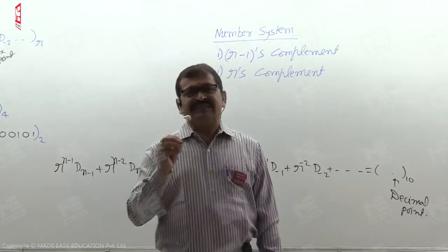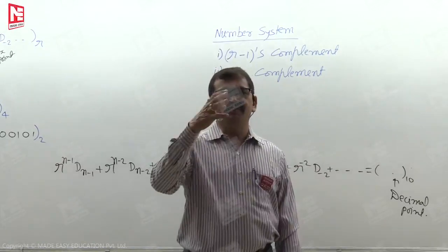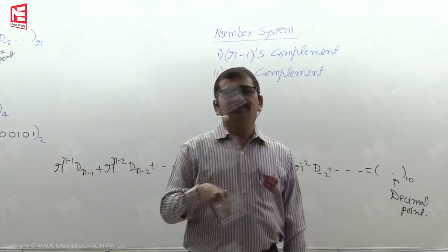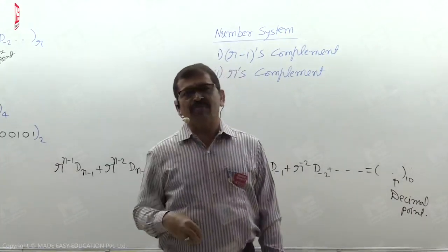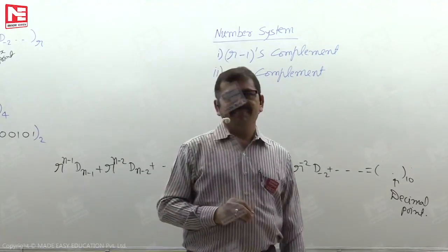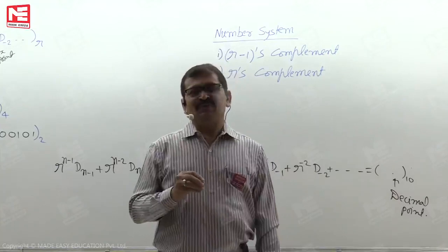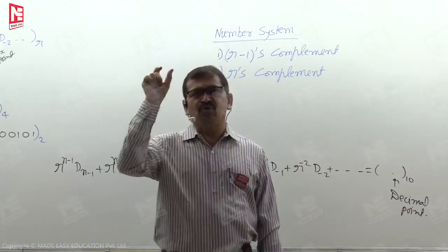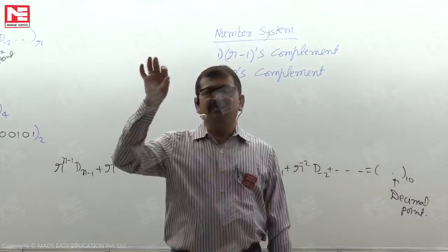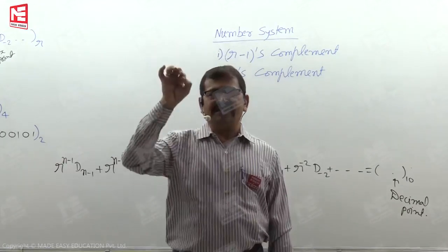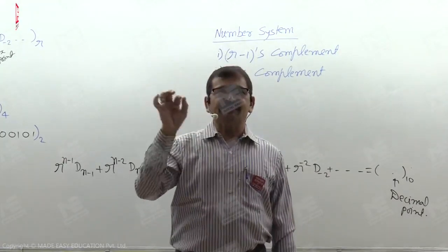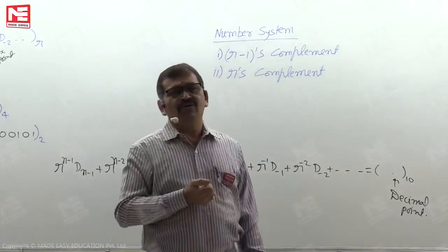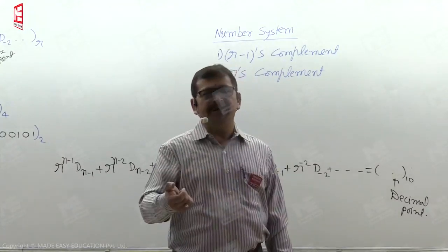When we subtract binary number B from binary number A, we prefer to do it as A plus either the 1's complement of B or A plus the 2's complement of B. If ready hardware is available to perform addition on two binary numbers X and Y, the hardware performing X plus Y can be used with a little additional hardware to perform subtraction of binary number B from A.